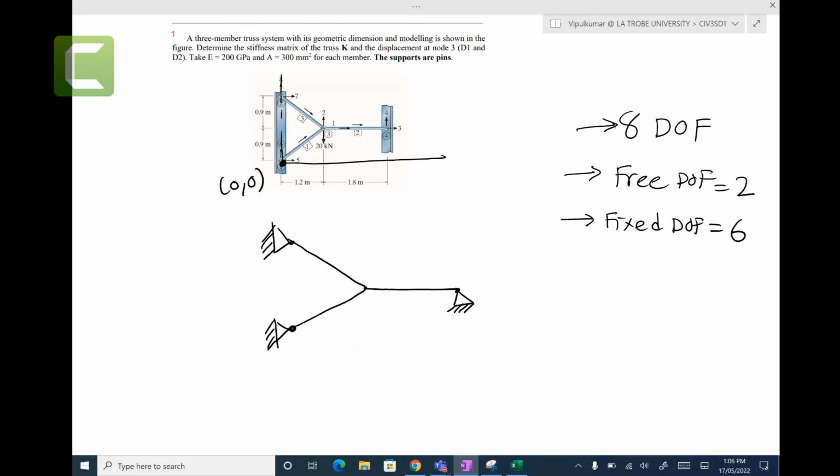Rather than if I take it somewhere here, then this will be a negative coordinate, negative, minus, plus, and it requires some attention. Why would I make my life hard by choosing something that is not friendly? Generally it will be given. If it is not given, just take your truss, go far left, far bottom, and pick the point. Okay, so that is your starting point.